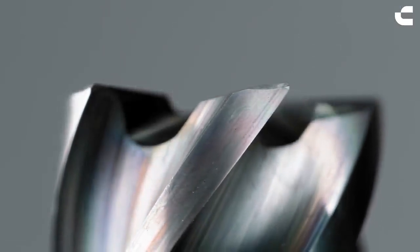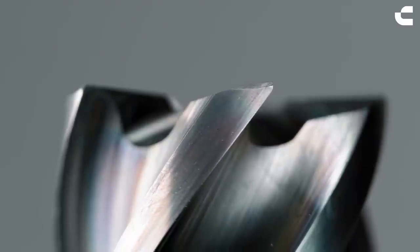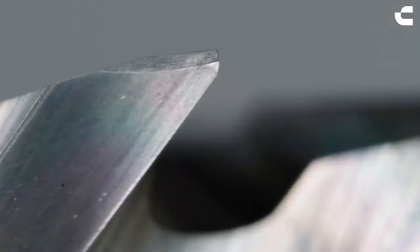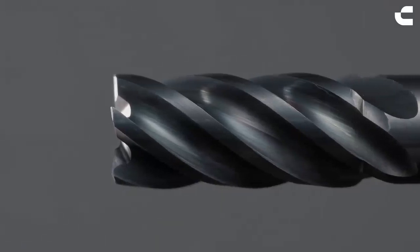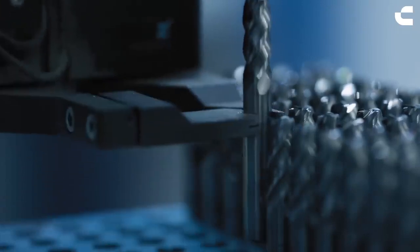After the grinding process, the cutting edge is extremely sharp, which is often not optimal for the cutting process. A slightly rounded edge can offer improved performance based on the material and cutting conditions. A rounded edge with a radius of 2 microns can improve the tool life by up to 10 times based on the material and cutting conditions.